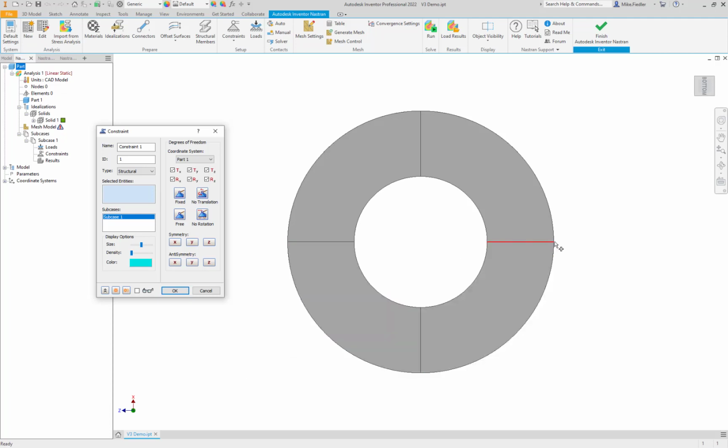Likewise, anything between 3 and 9, if we give this internal pressure, those should move purely in the z direction, but not x. So that allows me to add some constraints to the model where we can accomplish the constraint that we need without over constraining our geometry.